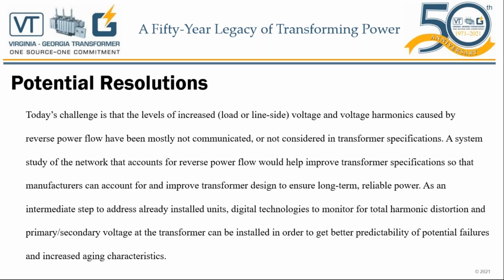Today's challenge is that the levels of increased voltage and voltage harmonics caused by reverse power flow have been mostly not communicated or not considered in transformer specifications. This is okay, as our systems are developing with the new renewable energy resources. As we spoke at the very beginning of this presentation, we are changing from traditional to modern. That means we are learning, and as we learn, we are adapting ourselves, our transformer specifications, materials, and we will design and we will build transformers to overcome these additional stresses coming from the reverse power flow.